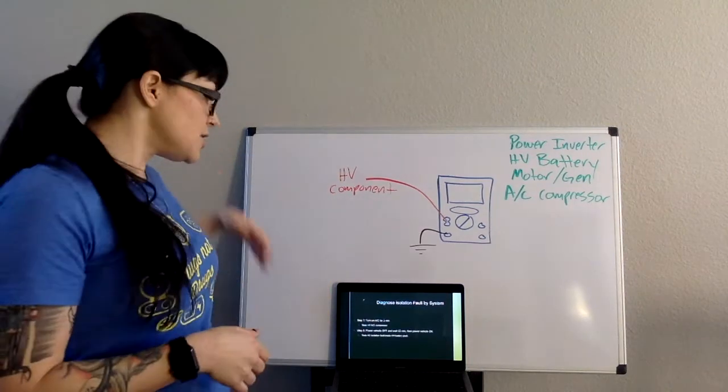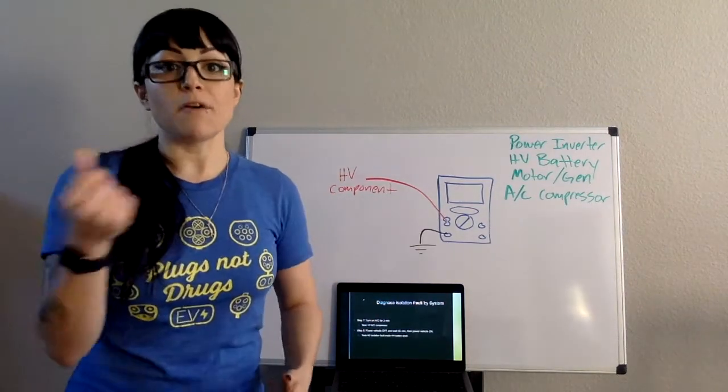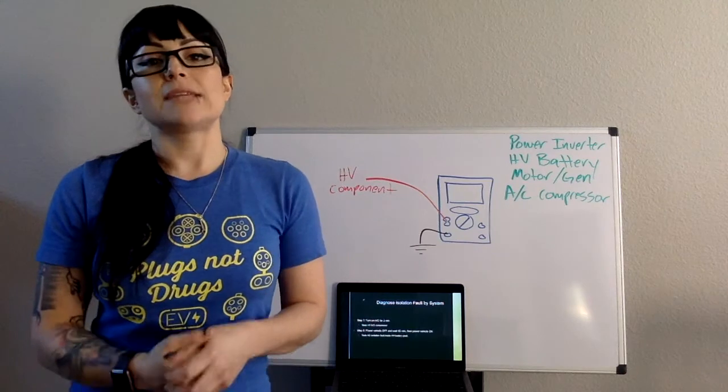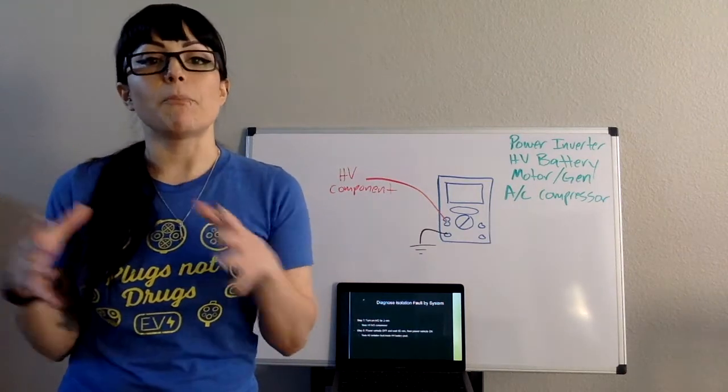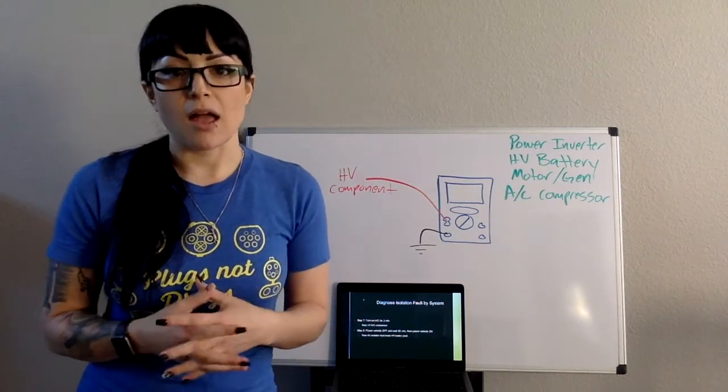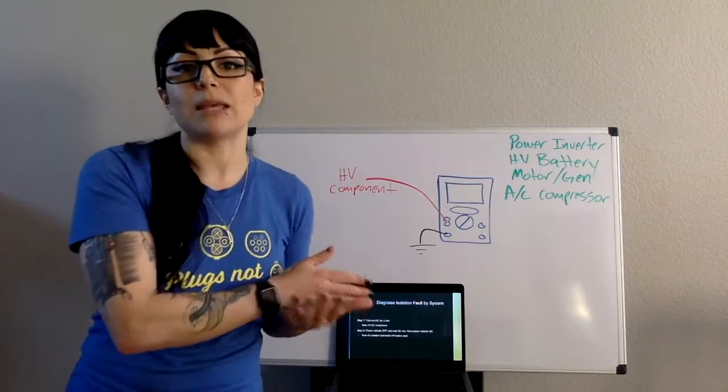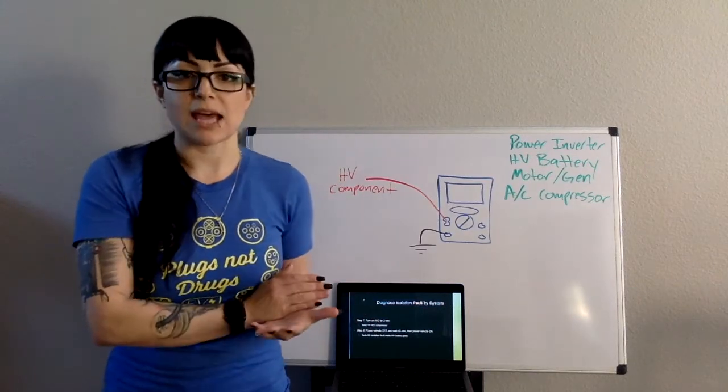After that 20 minutes, you power on the vehicle. If a fault pops right up, you know that it's actually going to be the AC fault having to do with the battery pack itself. And then again, back to the beginning, we're going to have to test that battery pack.